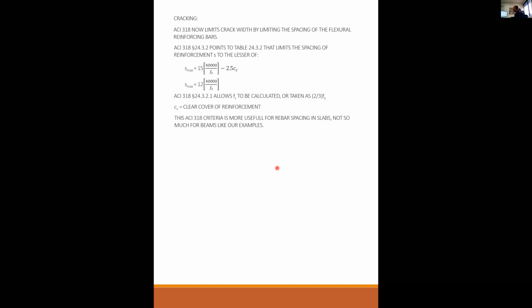That's your decision. You can use a 32-inch deep beam if you wanted. That's your decision as a designer. But you have to choose a beam depth, right? So you don't round up D. You use the minimum D to find the minimum height of the beam, and then you choose a beam.